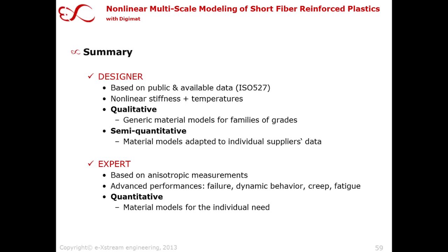Then the next level is really the expert level. So this is basing on isotropic measurements, and this covers all the advanced performances that you can find. So failure, dynamic behavior, creep behavior of your material, and if we look into the future, also the fatigue of short fiber reinforced plastics. And this is what I call really a quantitative approach to material modeling. So it's really material models for the individual need of our customers.